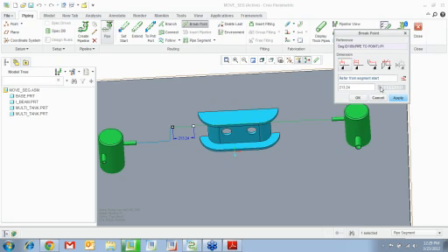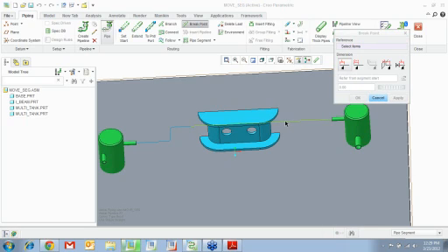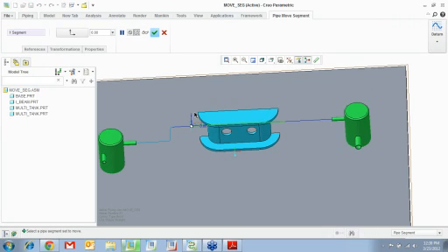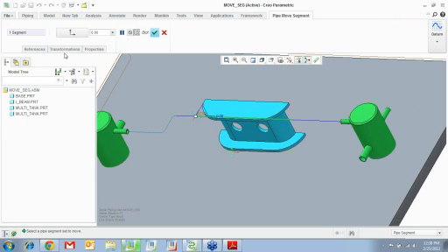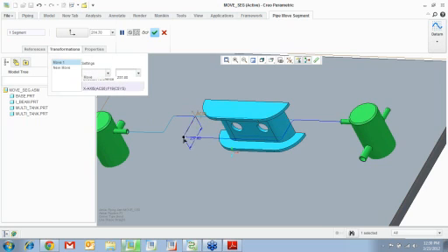Okay, so you can move it however you want. Say OK. Then insert another break. Say on this side. OK. Now you can select that pipe and say move. Now when you move, you see this is very similar to your copy paste fashion. Okay, move in the X direction, you can drag it. See that?